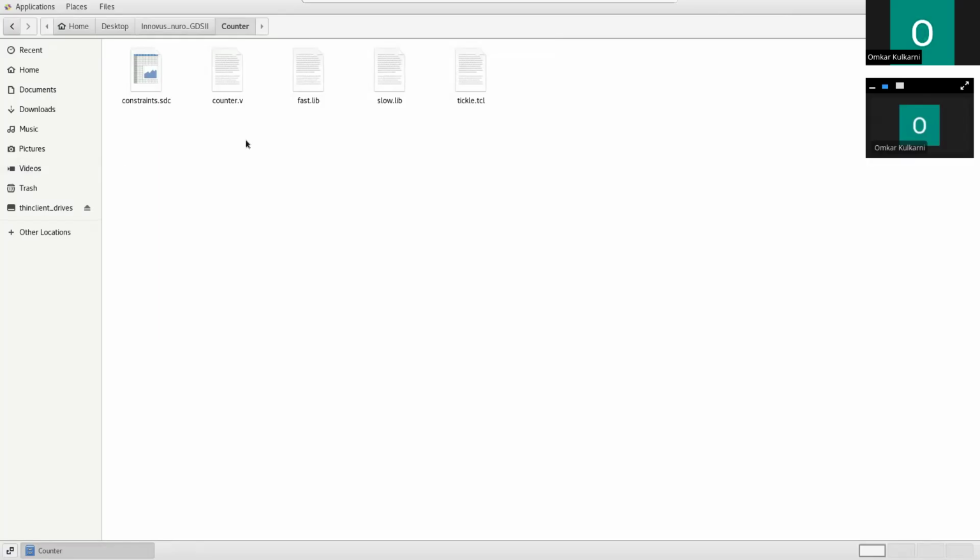Hi everyone. So in this lab, we will be going to design RTL to GDS, where RTL will be the Verilog code which we will be writing, and the GDS is the Graphic Design System 2 file, which is the mask-friendly floor plan, where this GDS will be sent to the foundry so that this can be fabricated.